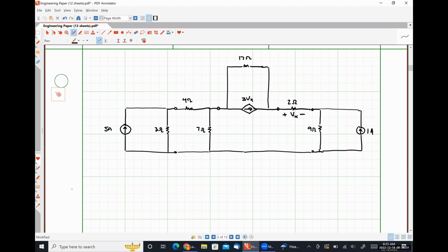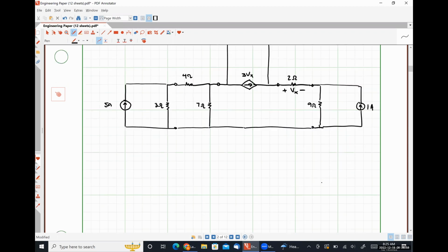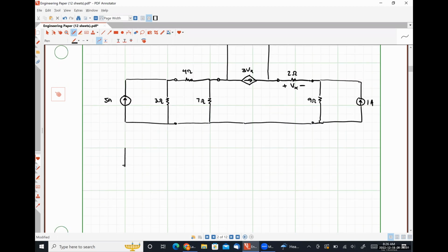All right. So I've drawn these terminals the way that I have because how I like to do this is effectively I disconnect our practical source, transform it into its opposite thing. So in this case, we're going to transform a current source into a voltage source and then reconnect it at those terminals. So the terminals help me to understand exactly where I put the new thing in, okay? So if we were to disconnect the 5 amp source in parallel with the 3 ohm resistor,